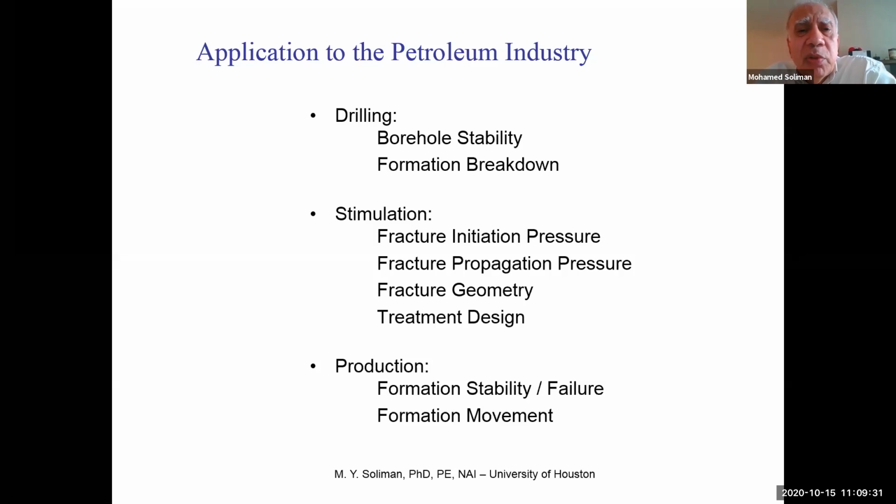We'll mention a few little things as we talk here. Formation breakdown: if your downhole pressure, or the wellbore pressure, is too high, you could fracture the formation. If it is too low, you could collapse the wellbore. So it's very important to understand all this relationship in rock mechanics and the fluid flow.